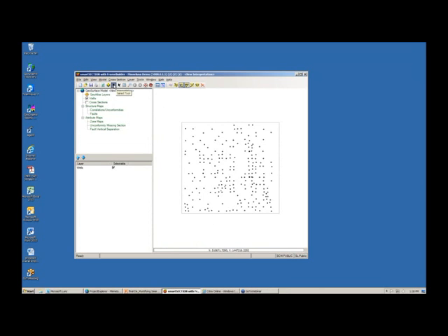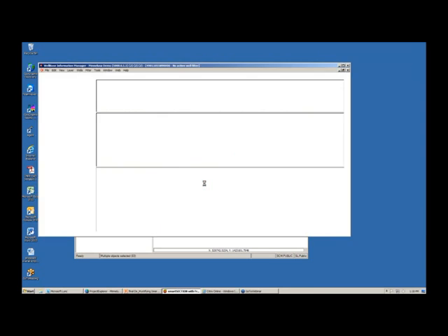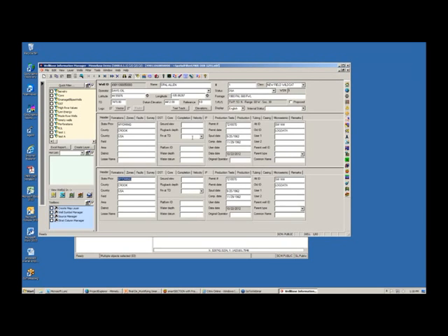Now we're going to assume that there isn't a filter made so that I can show you how to make a new one. Basically, you're going to come up to the Select tool and just click and drag a box around the area that you're interested in. Do a right mouse button, select View Wells in WellBase, and WellBase is going to open up. As you all know, in WellBase we can create spatial filters, and sure enough, one was created that has approximately 83 wells in it.